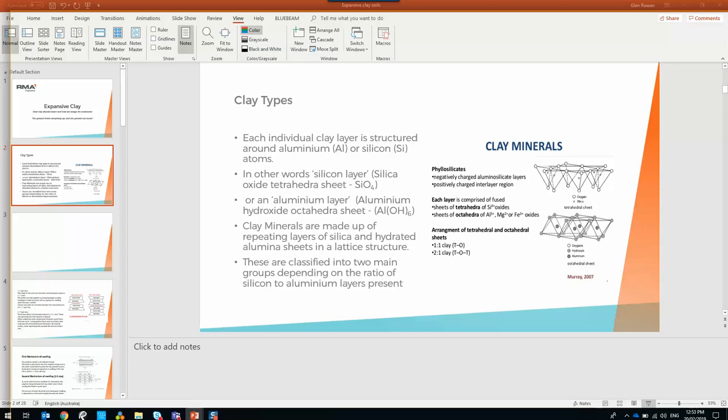And the other one, sometimes there was a theory that you use a big edge beam, like 1500 deep, as a moisture barrier. It's flawed as well because in the areas we're talking about, the soil moisture content changes over a 3 metre depth, and also the soil can bind on the edge of it and drag it up as well. Then you've got to run services through the edge beam, and don't do it. Short answer.